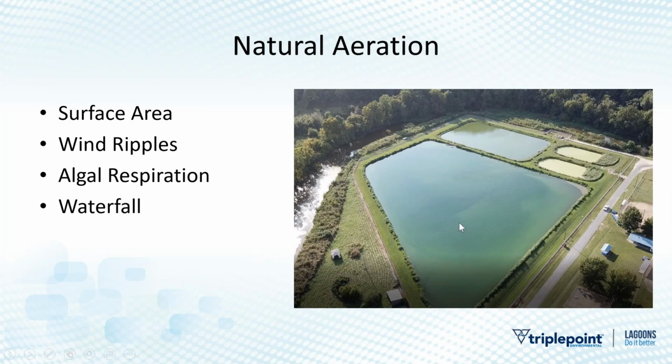It's the green stuff. It is kind of a double-edged sword though, because when those algae stop receiving sunlight, they switch their type of respiration and they actually start consuming oxygen again. So at nighttime, they're sucking the oxygen out of the water. Daytime, they're aerating your pond. And lastly, you might have a waterfall in your effluent or in other parts of your wastewater treatment process. When you get that turbulence and water's being churned up, oxygen will be transferred in those applications.